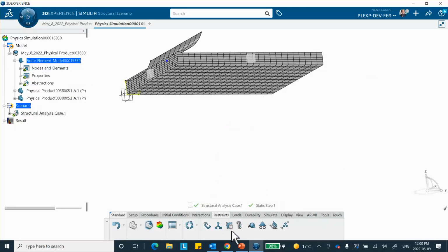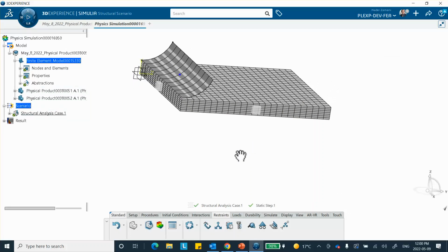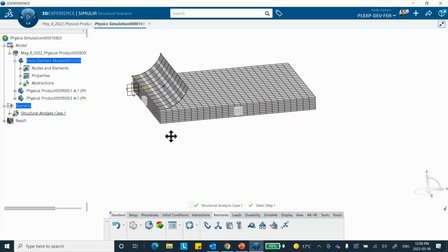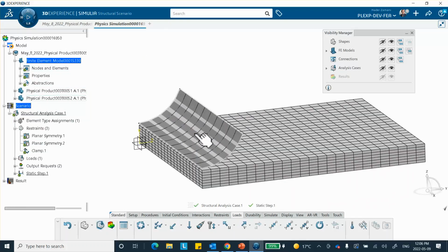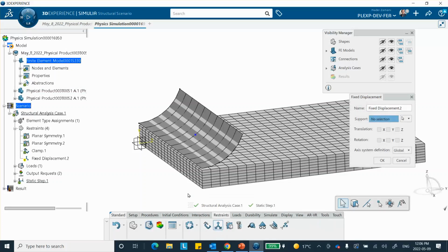So here's the clamp, the bottom here, right there. See that? This is what it does when it clamps. No, there's no other identifier there. Okay, now the reference point, which is that center of mass, we're going to push it down only. We won't let it go anywhere except pushing it. Apply a translation to the reference point of this rigid body, okay? But fix other displacements. So let's go ahead and do a restraint, fix displacement of this point.